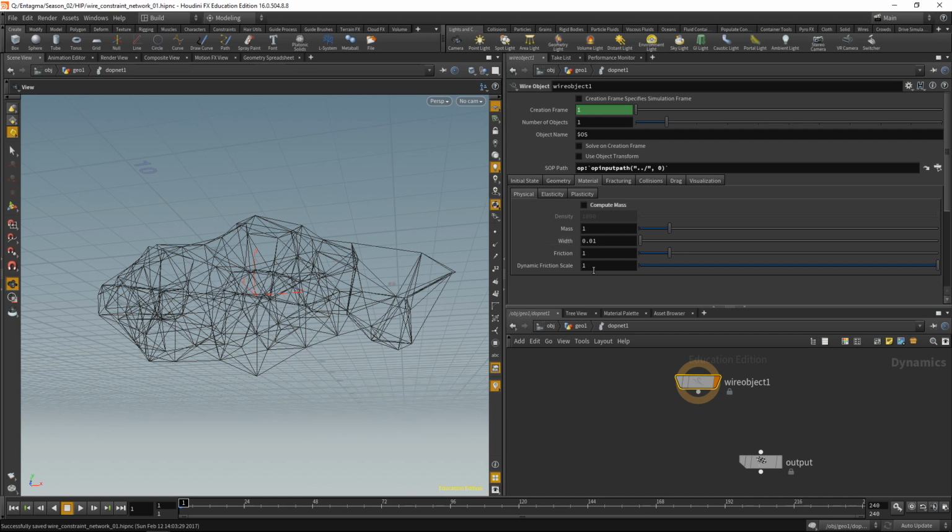That's fine. We can leave these as they are. And in the Elasticity tab, I will just increase the linear spring constant to be 10,000 instead of 1,000, and also increase the linear damping to 5,000 and the angular damping to 10, and I'm gonna disable the adjust for length and adjust for mass. I don't have a recipe for finding out these values. It's just what made sense and what looked good after dialing and fiddling around with those values. So these are the values that you're gonna experiment with.